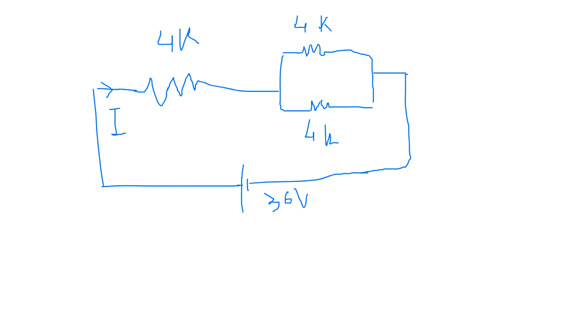So what is the way? Now you can see that here two resistors are parallel, right? Yes or no? 4 kilo ohm. This is not in the book. I searched, since this is a subject where you don't have the electrical topic, so I am getting it from outside. Anyway, just focus on how to solve it. So two resistors of 4 kilo ohm each. Whether these two resistors are series or parallel, who will tell me? These two are parallel, correct?